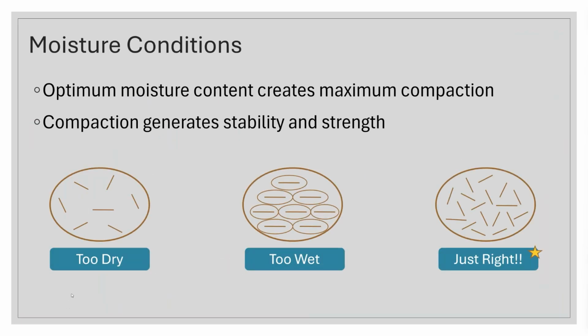Moisture has a big impact on how well these soils will behave, and different soil types will handle that moisture differently. Silts and sands don't tend to hold moisture in the same way that clays do. Clays actually have a chemically bound layer of moisture around them, so it holds onto that moisture a lot, and it also attracts more moisture. So I'm sure you're familiar with clay soils that when they get wet, they kind of swell, and then when they dry out, they shrink back down. So we have a lot of volume change. That's not optimal for being the support structure for a pavement.